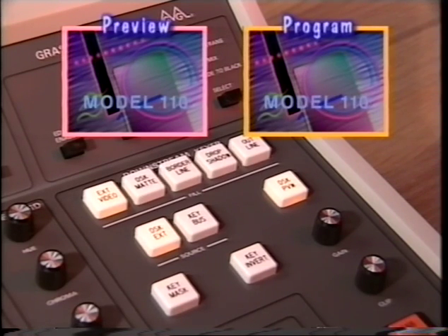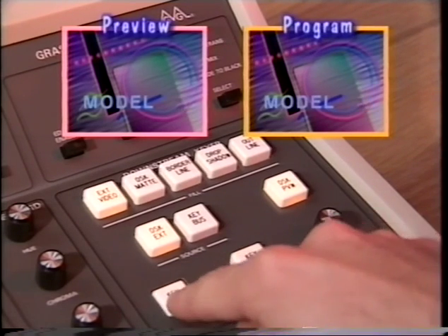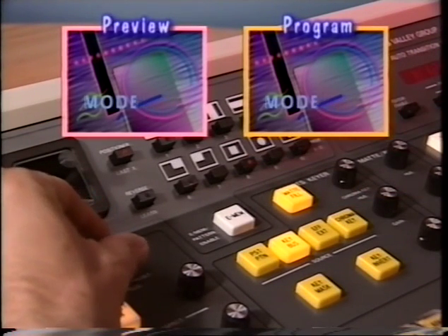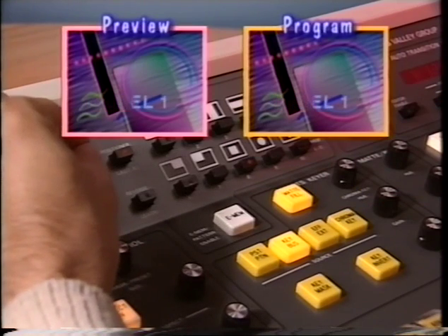As with the effects keyer, you can mask off areas of the key so that no keyhole will be cut in that area of the background. If you want to do this, select Key Mask. Select a white pattern and adjust the pattern controls to mask the key with the pattern.